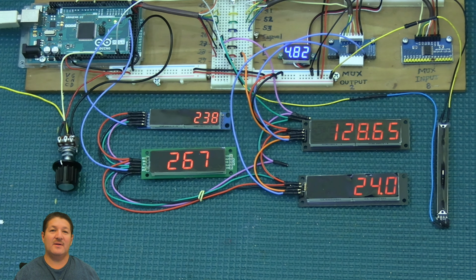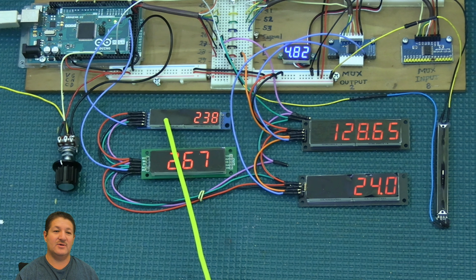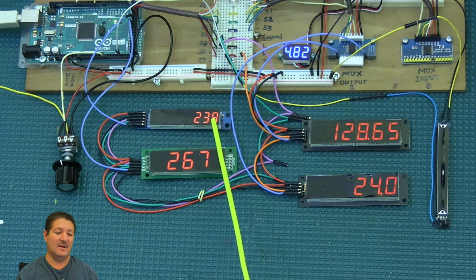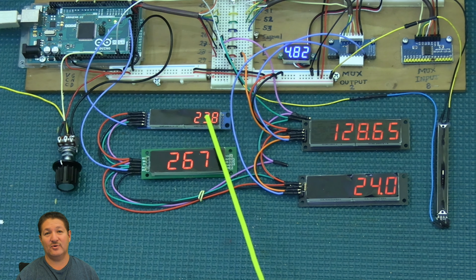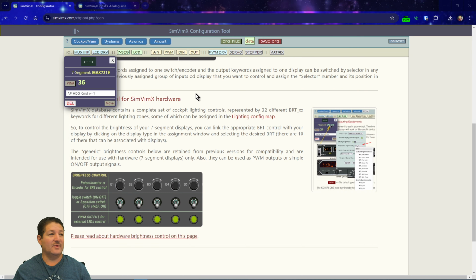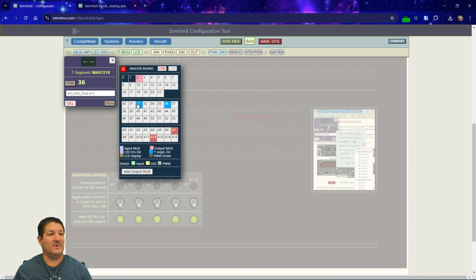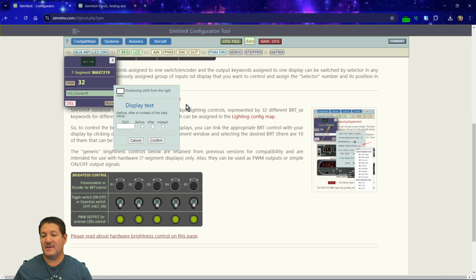All right, going along the same concept with the offsetting, let's say you wanted to put the two courses on this display. Because it has 8 digits, you can technically have 3 digits, 2 blanks, and 3 digits. So let's say you wanted to move this one over here to be course 1, and have course 2 on the right side over here. We'll go to the website, go to the one on pin number 32, which has course 1, click edit, and offset that one 5 spaces.